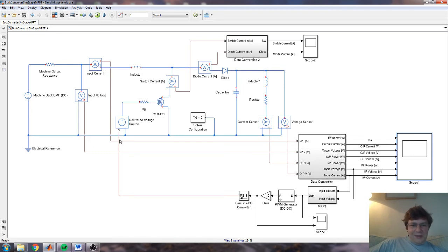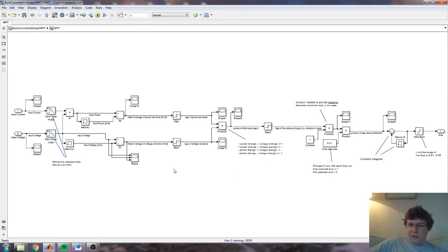If you think back as far as you can to the earliest electrical network stuff, you might remember that if you want to get the maximum power you can out of a Thevenin source, you've got to put a resistance across there which is equal to the Thevenin resistance, and then the voltage will be shared half each, and the current will be a maximum, and so forth. And that will give you the maximum power transferred. So that's what we ought to expect to happen, and the whole thing looks like a big DC to DC transformer.